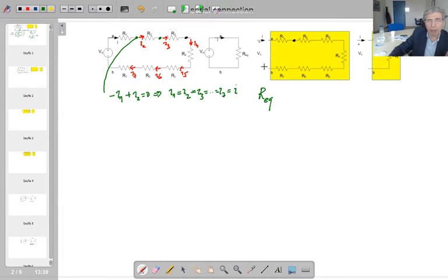We know that an independent voltage source does not change wherever it is connected. Therefore Vs stays as it is, and if we prove that this I and this I are equal to each other, then I am going to say these 7 elements are replaced with this equivalent resistor. The currents do not change, therefore this resistance value is the equivalent resistance value for these 7 resistors.